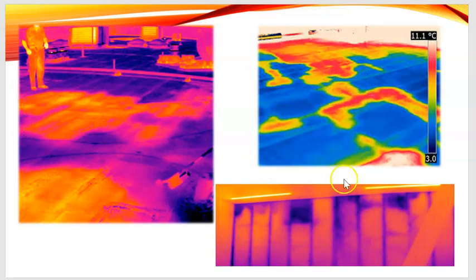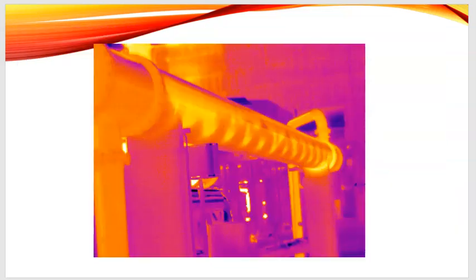There are just a couple of other applications. This one I found interesting because you can see where the framer or the insulator on the house ran out of insulation and decided not to put in that last foot. What does it matter, I'm just going to insulate. Well, you can see the studs there, but all of a sudden you see this big dark spot right up there, and it's nice and flat. Obviously, by the way, this would be a wall. There's sheetrock and paint over the top. You cannot visibly see that, but yet with the temperature cold outside and warmer inside, you can see that it's transmitting the heat out quicker, so you've got a colder temperature right there. Call the framer or the insulator up and tell him you want your money back.